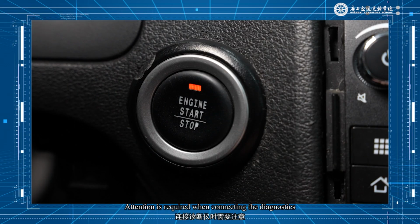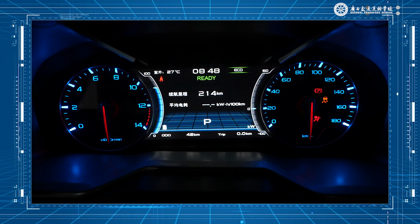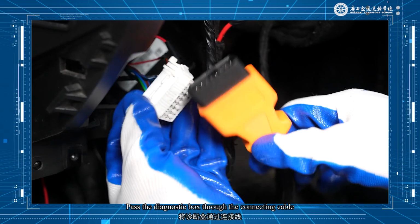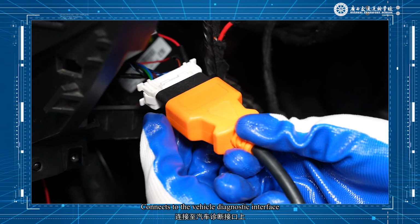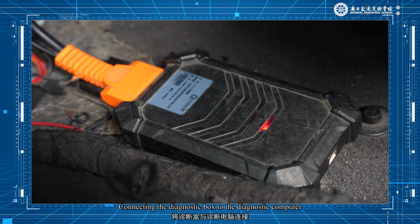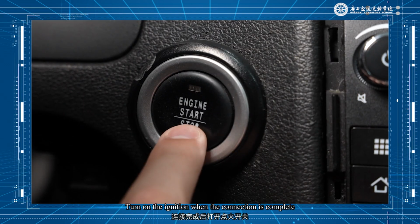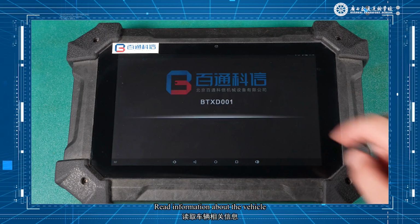Attention is required when connecting the diagnostics. Turn off the ignition first. Connect the diagnostic box through the connecting cable to the vehicle diagnostic interface. Then connect the diagnostic box to the diagnostic computer. Bluetooth can be used to connect the diagnostic box to the diagnostic computer. Turn on the ignition when the connection is complete. Read information about the vehicle.